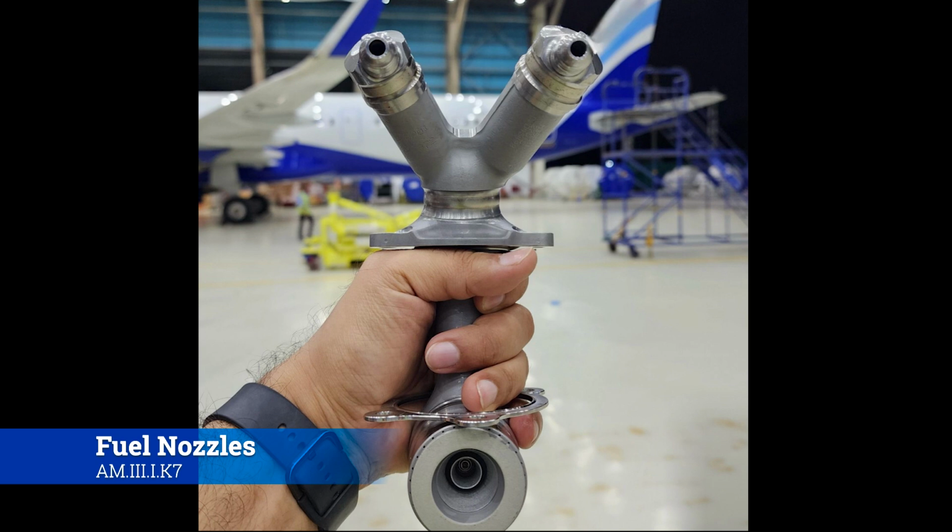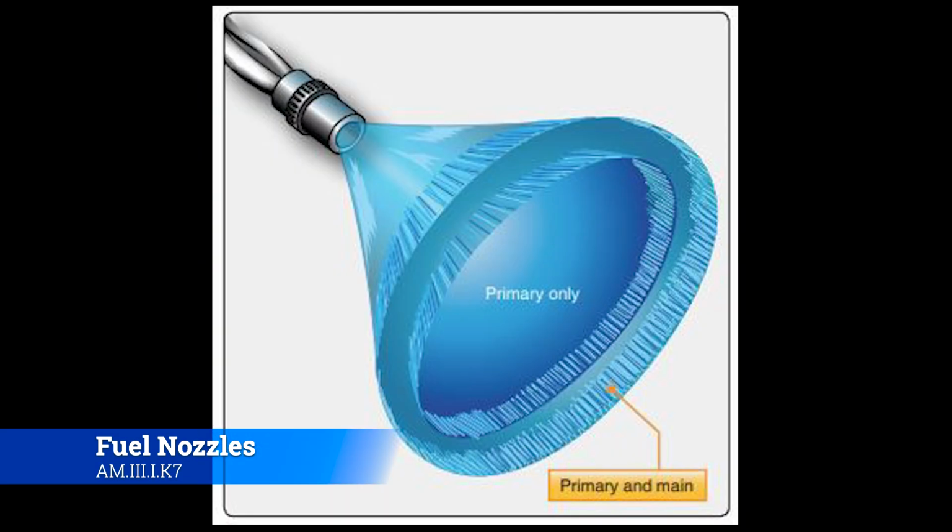Neither one of them had two different fuel ports, and the one off the CFM56 was kind of craned up and curved on the inside. This one looks like it just simply sprays directly out the bottom there on the backside of the combustion chamber. The point being is that every single one of them is different, and every single one of them is there to serve the exact same purpose, to get the right spray pattern, so that the engine can ignite correctly. Okay, so this is an example of a spray nozzle.